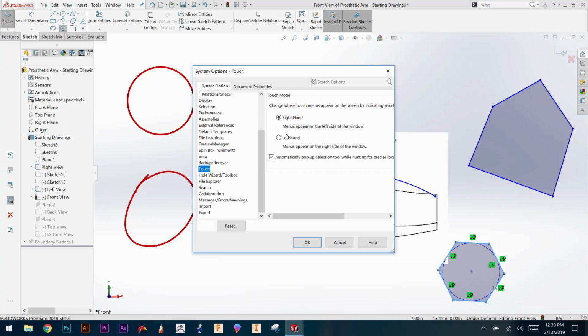Just to reiterate, the question is whether there's an advantage to editing splines in multiple planes first rather than creating a single spline and then projecting onto a surface. I would say that getting really familiar and comfortable with sketching in 3D and editing in 3D is really powerful because you're not having to swap in and out of sketching and using other features.